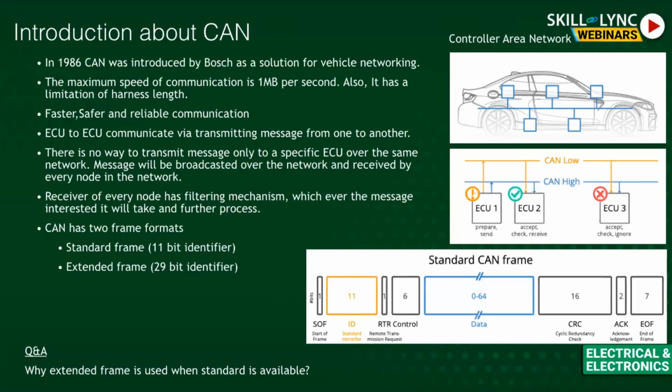The 7 will be sent over, and after receiving it, ECU2 will also sum up the data and see whether its sum equals the CRC or not. If both are equal, whatever he sent, I have received correctly. If it is not correct, I could have got a different count, not 7, maybe 8. That is how they re-verify that the message transmitted is proper and what I have received is correct.